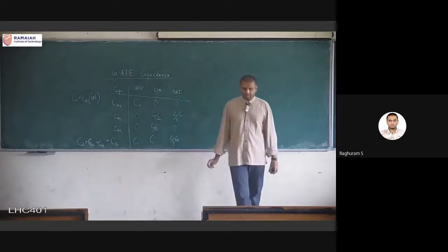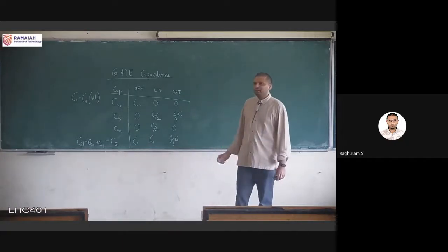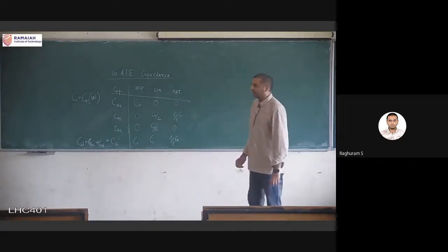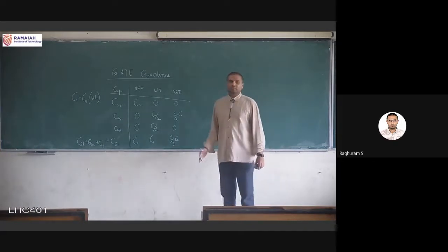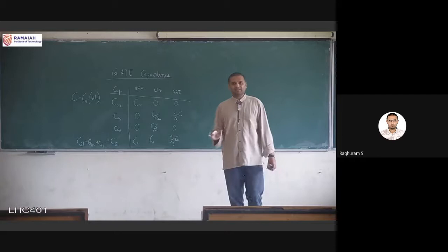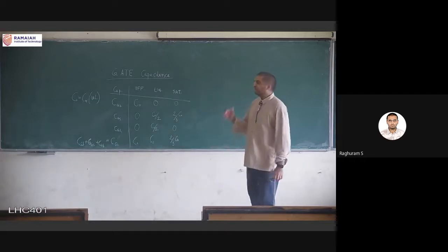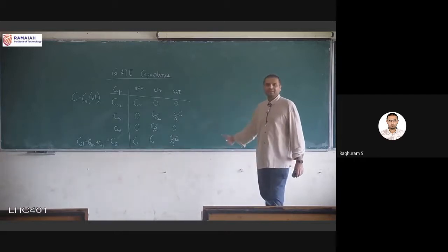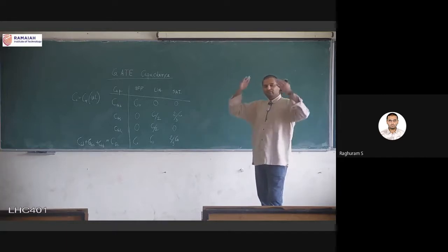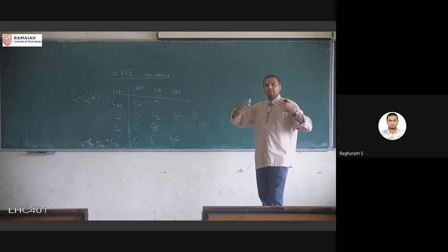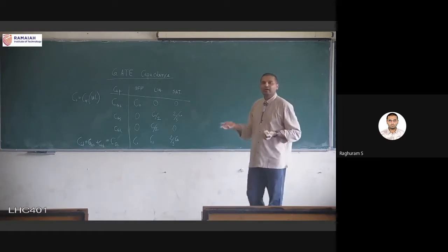So this is the summary of the gate capacitance, the first component of the capacitance that is associated with the structure of the MOS transistor, also called a parasitic capacitance. Nobody intentionally manufactured any of these capacitances. There is only a gate terminal, there is a substrate terminal, but it behaves like a capacitance. That is the whole idea of this model.